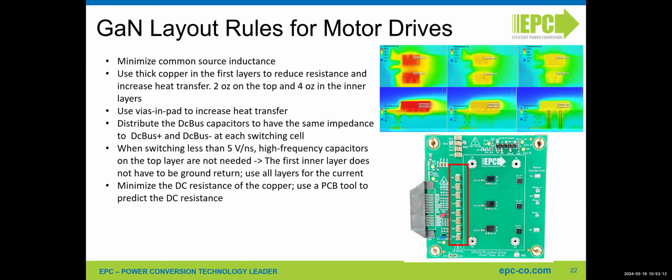We are still testing this board. We're talking about 20 amps RMS steady state, but we still haven't finished the test, and we will see if we are able to go even above 20 or even 25 amps RMS steady state, and then we need to see how much we can do in peak operation. Peak operation depends on your thermal capacitance.